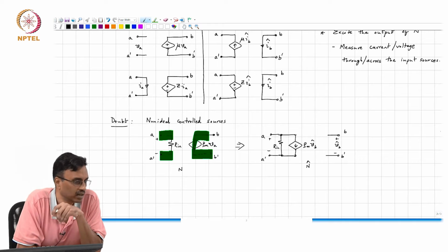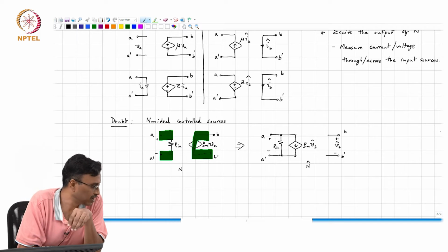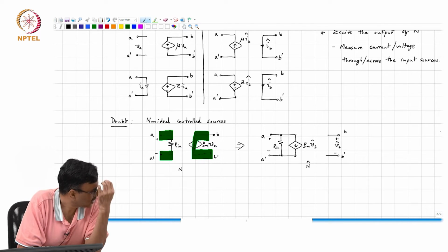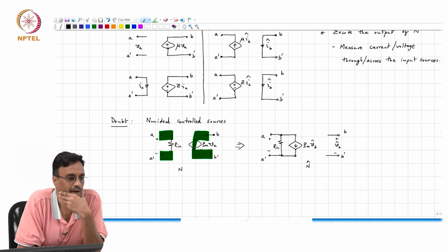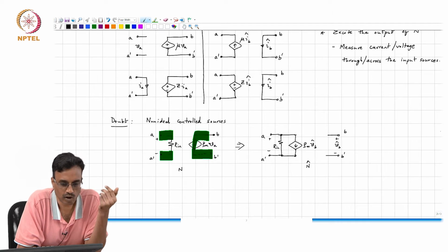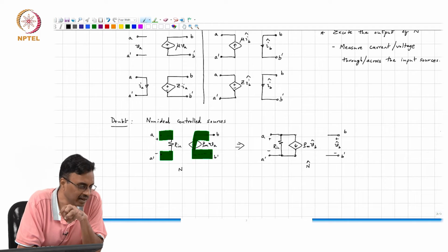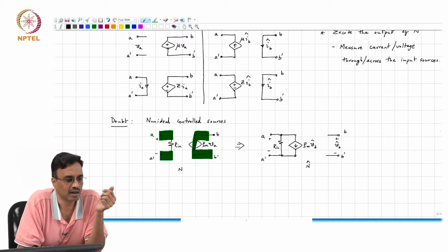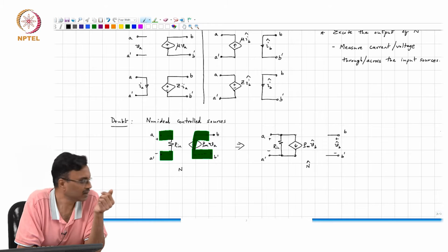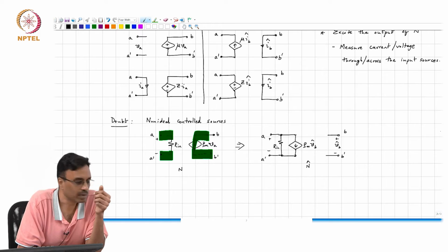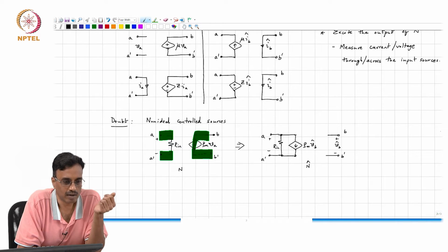And when we go a little further, we will see together that when we write down the matrices for circuits, which as you know are all solved on a computer using matrix techniques, it just turns out to be a trivial transformation of the circuit matrices, and therefore this is routinely used in SPICE. Every time you run a SPICE noise analysis, it's used.